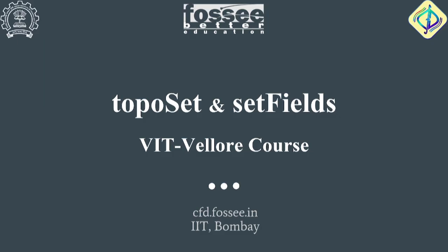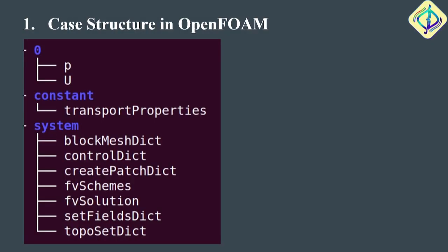setFields is more widely used in multi-phase simulations. You will learn multi-phase in the next class, so I'm just setting up the building blocks for the next class. Okay. So again, we are familiar with an OpenFOAM case structure. You have the zero, constant, system folders.